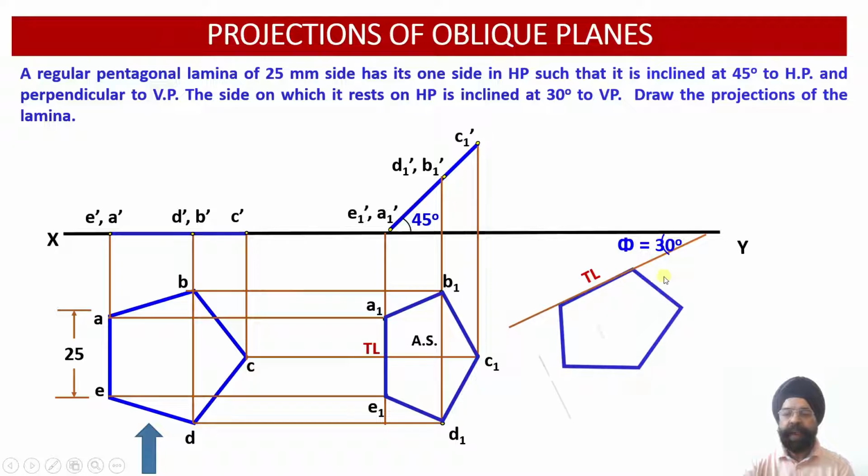So please see how we can transfer this particular image over here. Please be very careful. I am going to first of all draw this locus line, and onto this locus line I have to transfer this picture. How can this be done? Very easily. I have to measure rectilinear distances only.